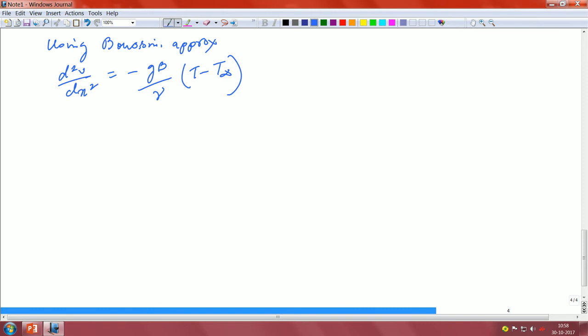But of course, this particular expression is equivalent to the Poiseuille flow, the Hagen-Poiseuille flow, in forced convection, right. Okay. So, it is the natural convection equivalent of the Hagen-Poiseuille flow, but it cannot be solved in such a nice way as we did in the case of your Poiseuille flow.